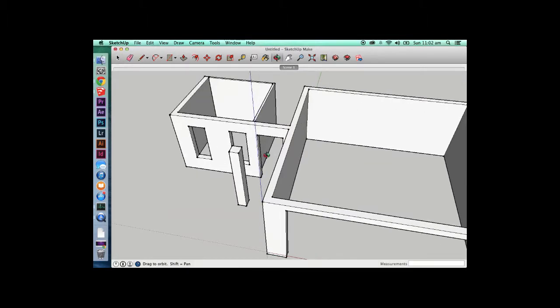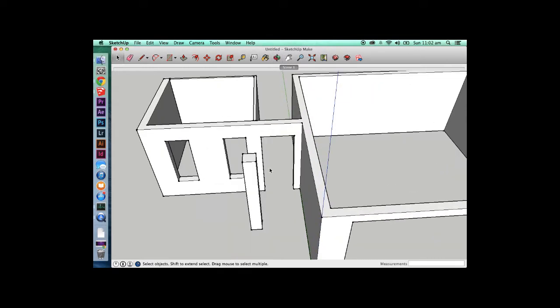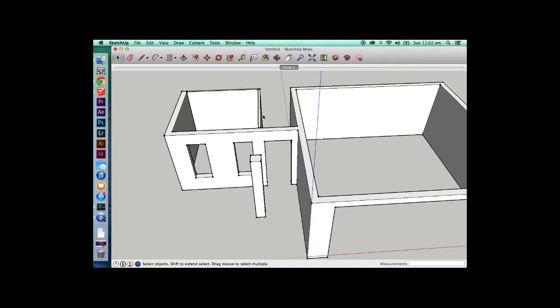Now, doorways, they range in size. Usually entry doors are 900 millimeters wide. Internal doors are 900 millimeters wide. They can be 800 millimeters wide. You can get 1200 entry doors. You can get double entry doors, which are 1600 or 1700.